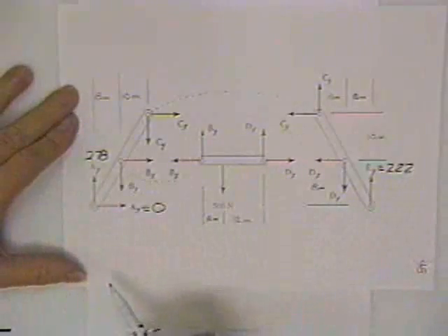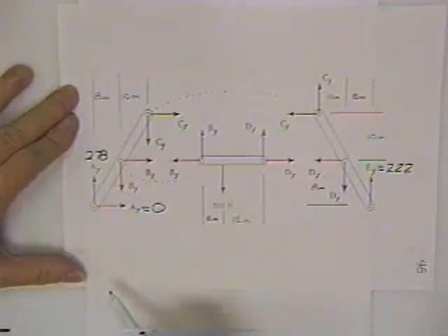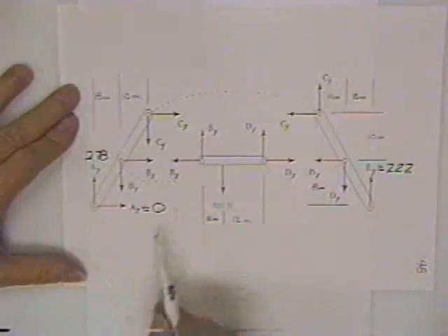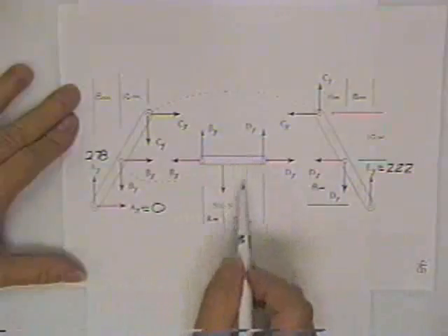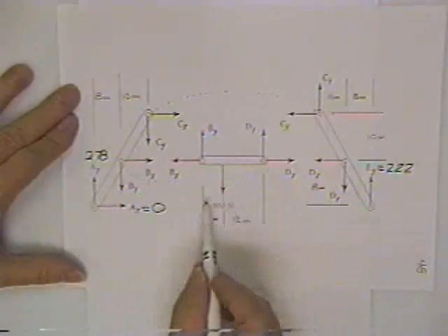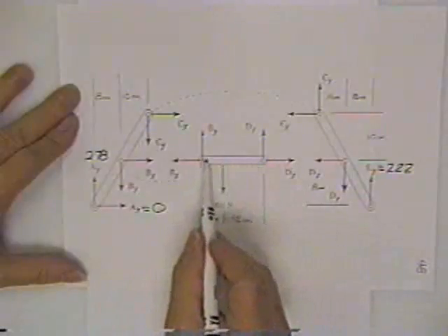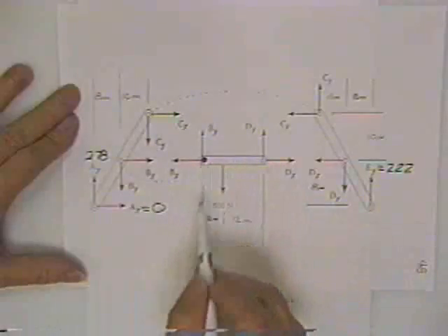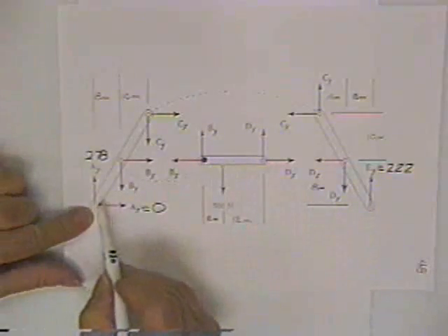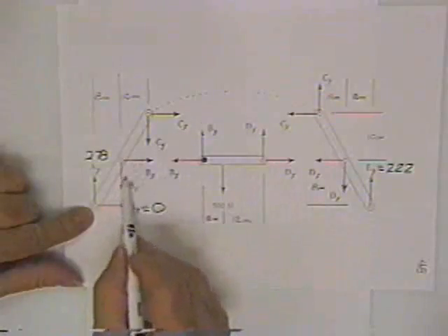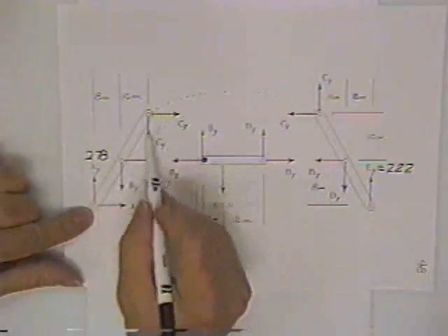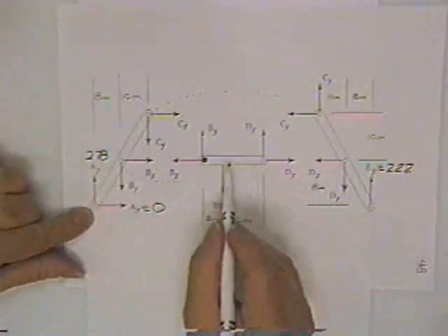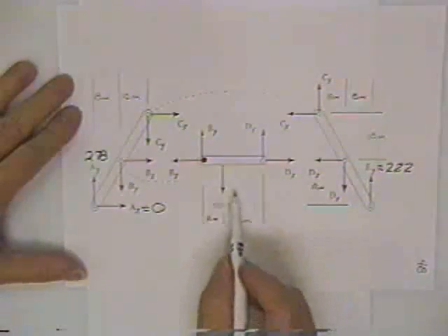Now, these can be put in equilibrium by statics. But your sum of your moments equation is always the most powerful equation you've got. If you ever see a horizontal or a vertical member, go towards that first. Because on a horizontal member, a lot of unknowns pass through one point. This one and this one, ooh, and this one too. Whereas on this slanted member, if you sum moments about this point, trying to get rid of these two unknowns, these two rascals here still have moment arms. So go towards a horizontal or a vertical member first.